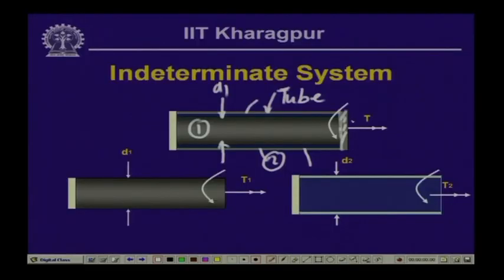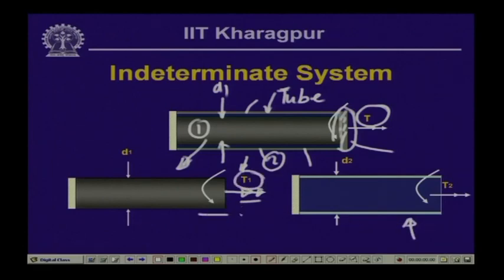Supposing we take off this rigid plate and take out the shaft over here. So, this is the internal solid shaft, which is subjected to a twisting moment, the vectorial notation of which is this, and let us call that twisting moment T1. That means the external twisting moment T, which is acting in the composite system, is shared by the shaft and the tube. The twisting moment acting in the central solid shaft is T1. The twisting moment acting in the tubular form is T2.